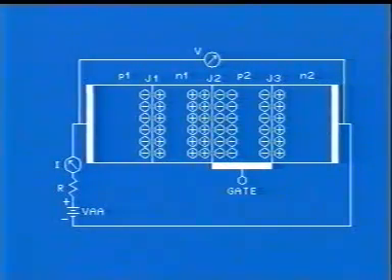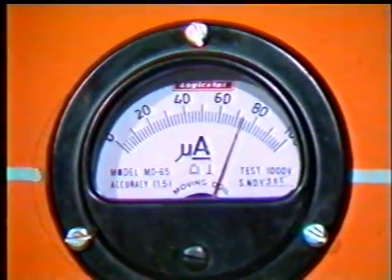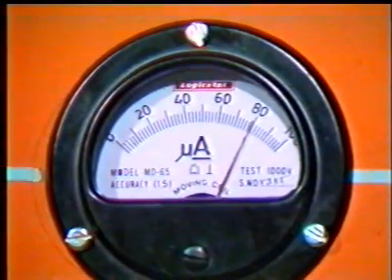When anode is positive with respect to the cathode, junctions J1 and J3 are forward biased and junction J2 is reverse biased. Therefore, the depletion layer at J2 is wider. In fact, the whole of applied voltage appears across J2. Thus, no current can flow through the device. However, while doing the experiment, we had seen a deflection of about 80 microamps. But why did the current flow?